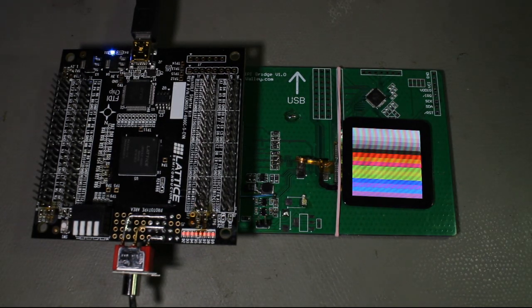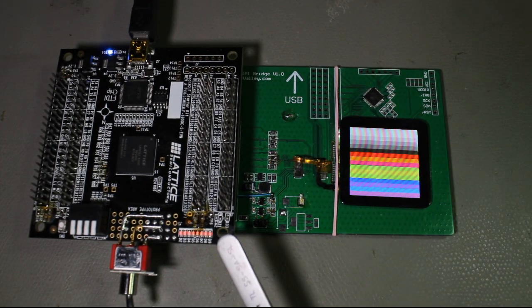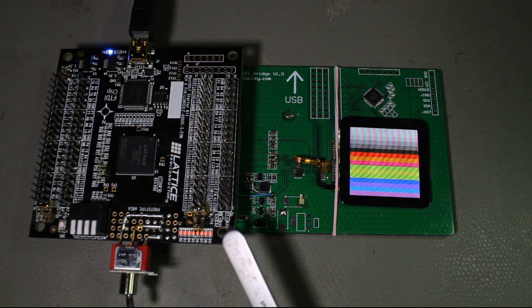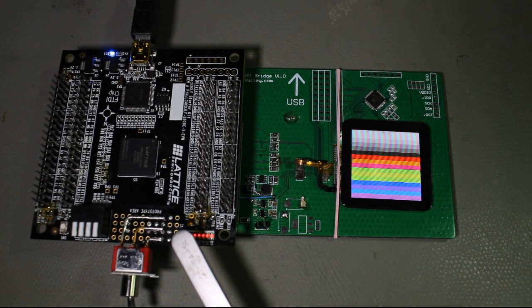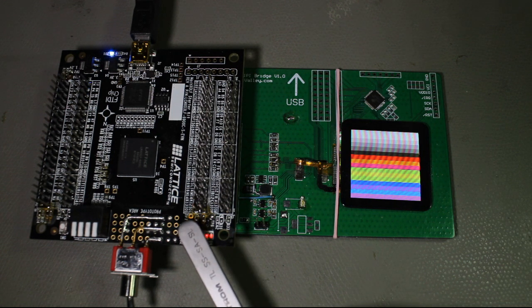For bank 0, I have set the VCC IO to 3.3 volt, though it should be 2.5 volt for LVDS, but I have compensated for that by making little changes in the resistor dividers here. And another bank I have set to 1.2 volt. This IO bank 1 is 1.2 volt for driving LP signals of the MIPI.